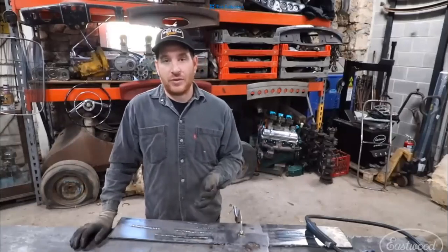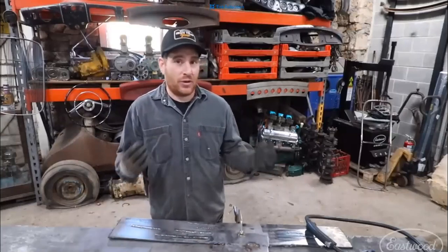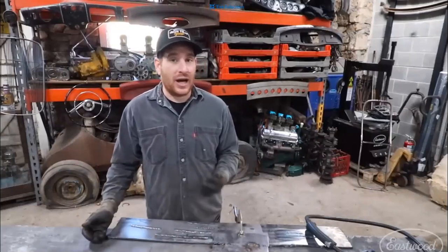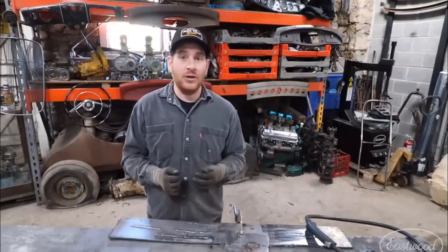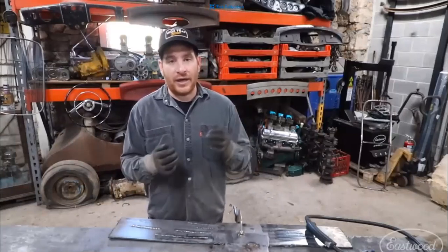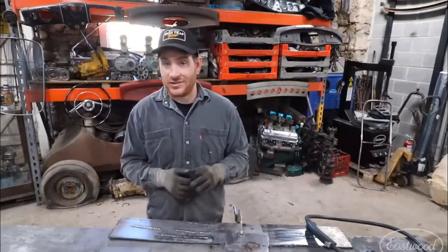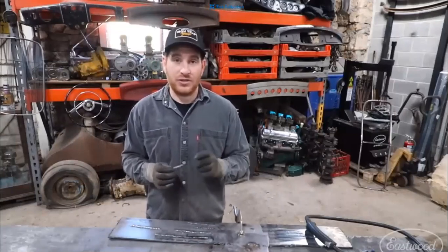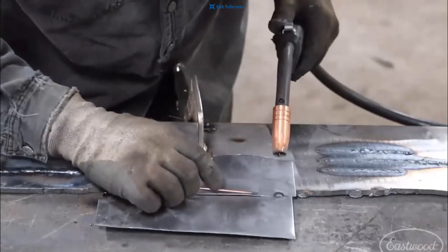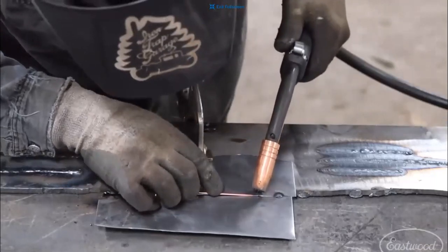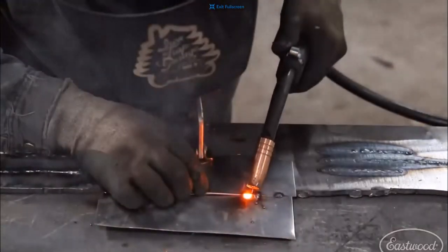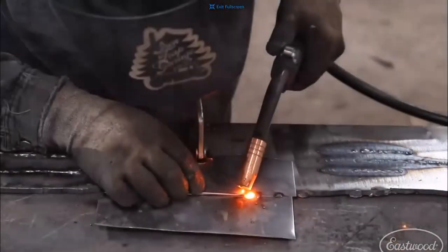So if you have a situation like that where you have too big of a gap, you've already tacked the panel in place, and you're kind of stuck, you can either use a copper backer to stick behind the panel to basically back the weld up, and it will help fill the weld up, and the weld will not stick to the copper backer. Or in some situations, if the gap is pretty small and you have a piece of filler wire that matches the gap, like I have here, I have a piece of 3/32 TIG wire that I laid down into this gap, and it filled up the gap, and then I used that as my filler.